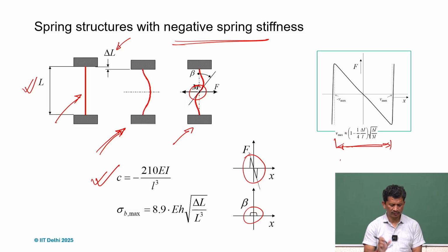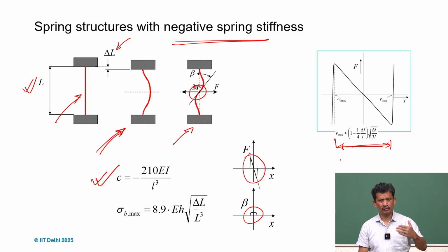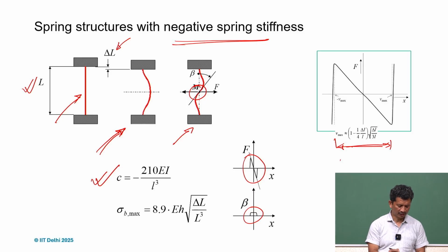That is the displacement range we are talking about, and in that range we get a negative stiffness because we always have to apply force negative to the displacement required. Of course you don't have to remember the formulas. If required, we can always refer to the relevant data or the formula, and if you want to learn more, we can refer to the literature. But what is important to understand is that if it's already preloaded and in buckled shape, the stiffness is negative.